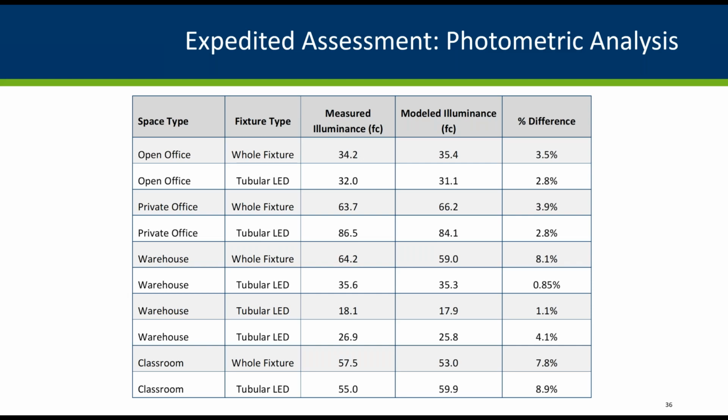In situations where model inputs are unknown, like partition heights or partition locations, the degree to which lights are task-tuned based on models should be reduced. For example, if the model predicts a space will be 20% overlit, the lights could be task-tuned by 10 to 15%. This may be relaxed in spaces with task lights, since occupants may supplement the ambient lighting to provide higher light levels only where necessary.